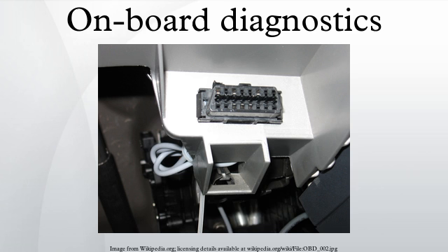The ADR 79/01 standard was supplemented by the ADR 79/02 standard, which imposed tighter emissions restrictions, applicable to all vehicles of Class M1 and N1 with a gross vehicle weight rating of 3,500 kg or less, from July 1, 2008 for new models, July 1, 2010 for all models. The technical implementation of this standard is essentially the same as OBDII, with the same SAE J1962 diagnostic link connector and signal protocols being used.